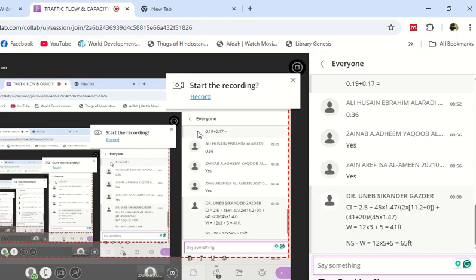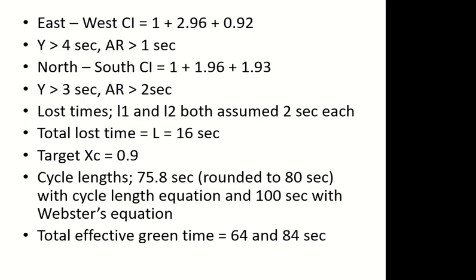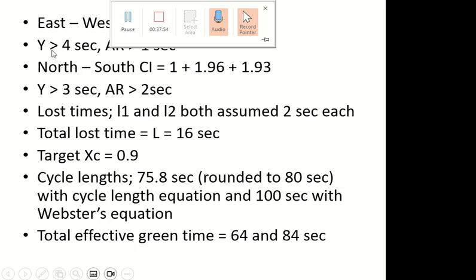This is how W is calculated. W will change according to the geometry of the intersection. The speed is the speed of the road, and the rest of the things are standard except capital G, which is the gradient. This is how these values are calculated.